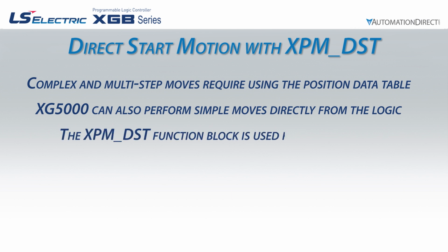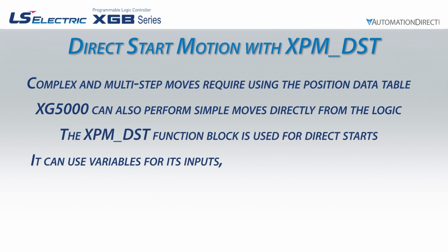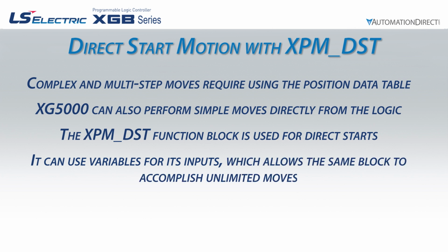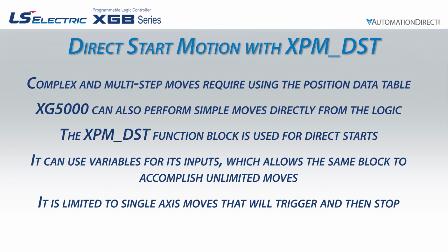The XPM DST function block can be useful for programming numerous moves with a single function block, as the direct start parameters may be altered between function block execution. This allows nearly unlimited simple moves without using up a lot of memory and processing power. However, they do have some limitations. For example, the direct start function will not work for multi-axis interpolated moves or multi-move sequences. These will require the use of the position data table.